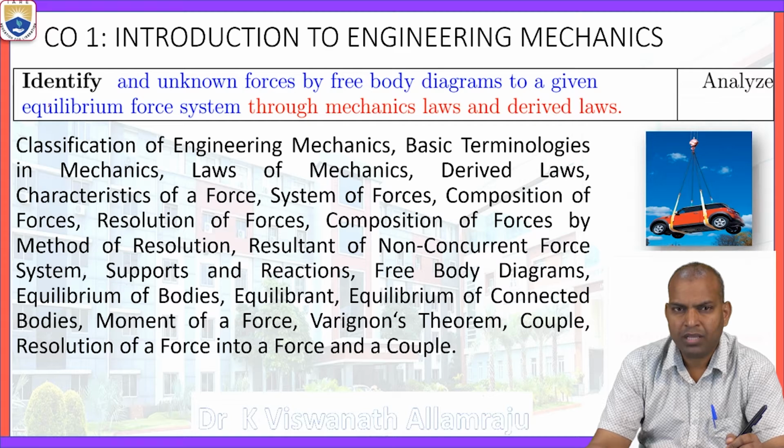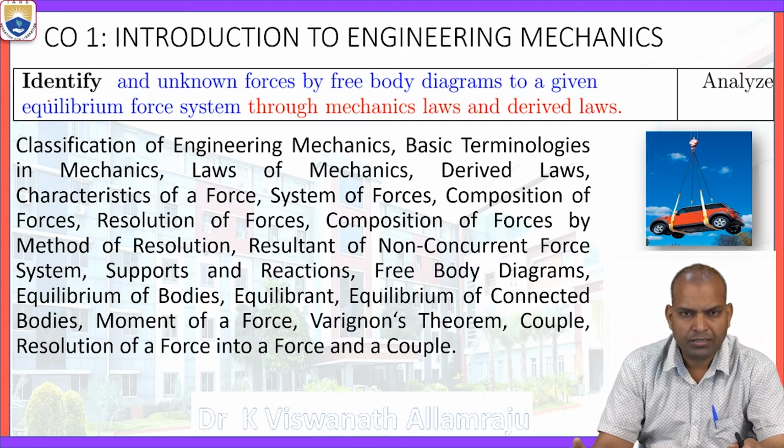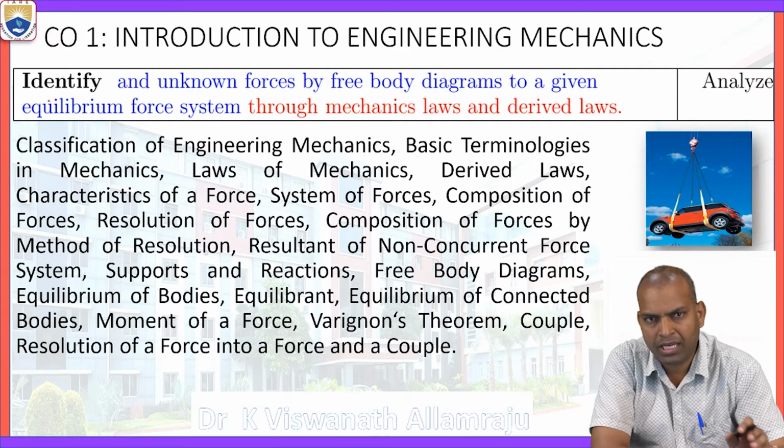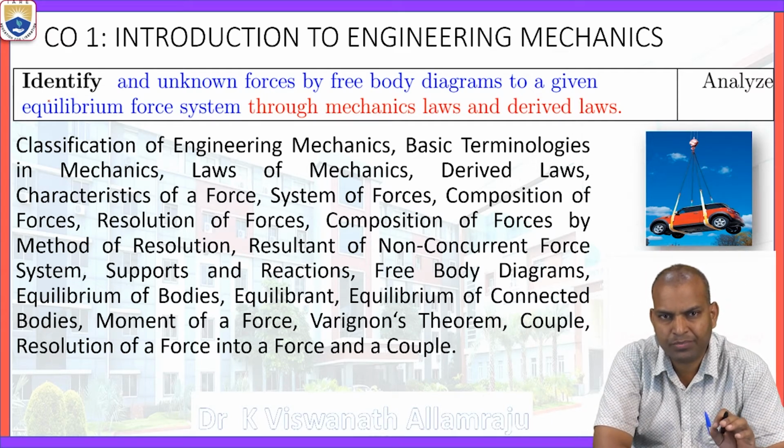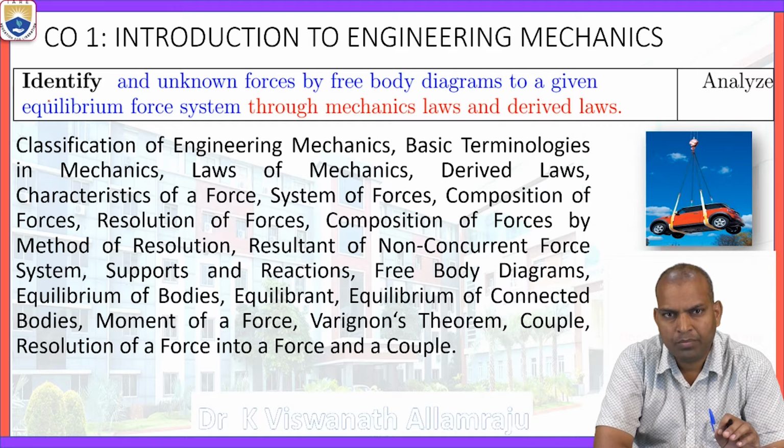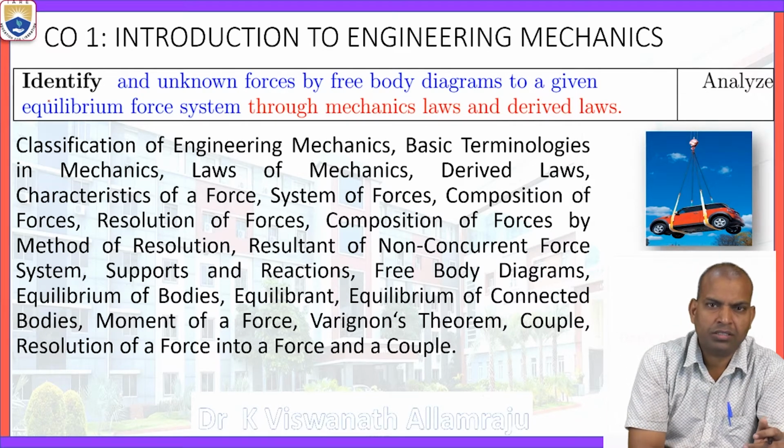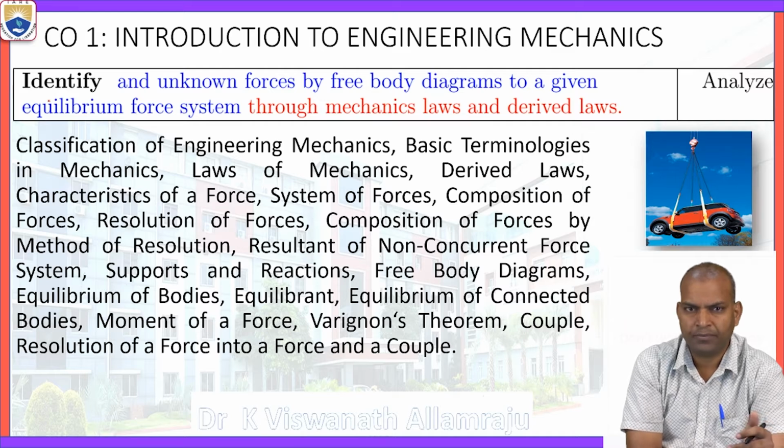If you want to apply the resolution of the forces, we need free body diagrams. What is a free body diagram? A free body diagram is the combination of action and reaction forces which are represented on a body by removing the supports. Then that body diagram is known as a free body diagram.